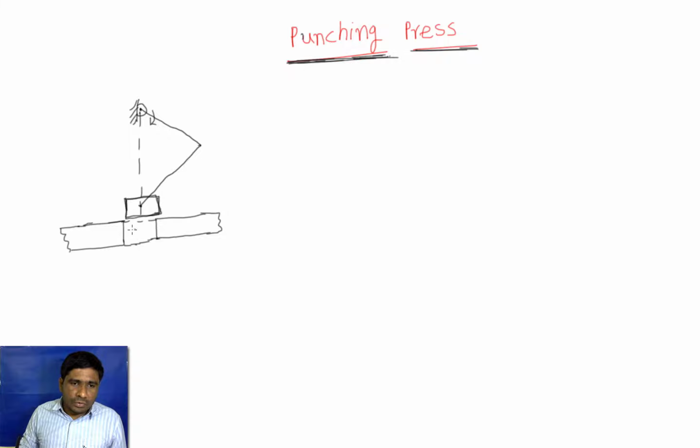Sometimes we need to make a hole, that is a punch in the plate, but sometimes we need the blank or the part produced by punch. So it depends on the requirement. So here let's take only punching operation. That means our primary aim is to make a hole in this plate. So this is the simple mechanism, and when this is rotating, this is what we call that crank. When the crank is rotating, this one is making to and fro motion. That is a slider motion.